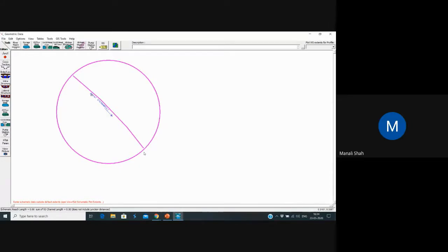If you want to plot that section of the Vishwamitri river exactly over here, then you need to work with another software known as ArcGIS, where you have to enter the digital elevation model of the Vishwamitri river section of which you are interested to work with. So that is another process, which is a very lengthy process.